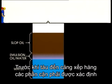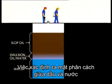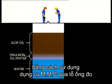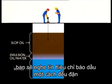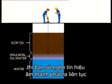Before the vessel arrives at a loading port, the slop must be measured and its weight calculated. But finding the interface between water and oil can be a tricky business. The task is to find the ullage of the interface. Again, we use the MMC through the vapour control valve. When the sensitive sonde is lowered through oil, you hear the steady signal, indicating oil. When the sonde reaches water, the sound changes to an intermittent signal.